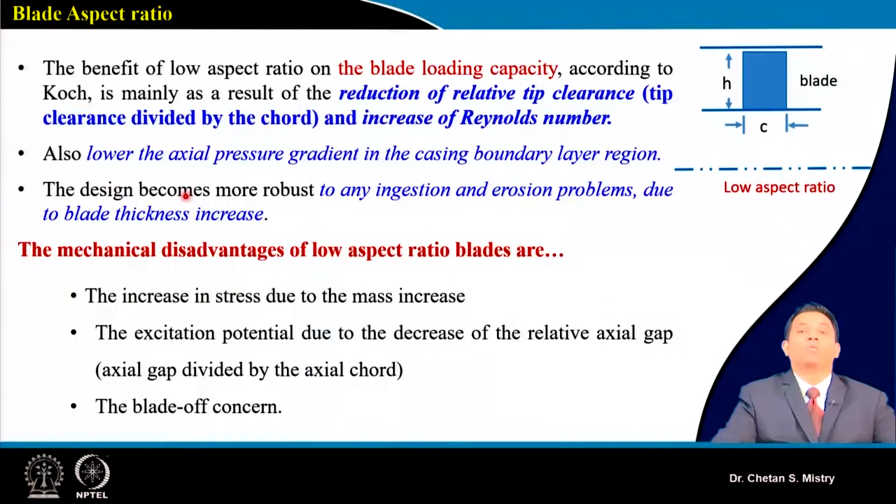So now when we are discussing low aspect ratio blades, we have special kinds of requirements. If you recall, when we started discussing engines, I was showing one engine, that was a Pratt & Whitney engine. I was showing one more engine, that was the GE Honda engine. And if you recall, I was discussing that for new engines, people are talking about wide chord blades. That is because our expectation in the sense of operating range is increasing.